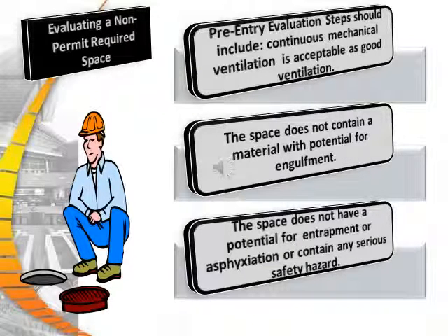Pre-entry evaluation steps should include that continuous mechanical ventilation is acceptable, the space does not contain a material with potential for engulfment, and the space does not have the potential for entrapment or asphyxiation or contain a serious safety hazard.